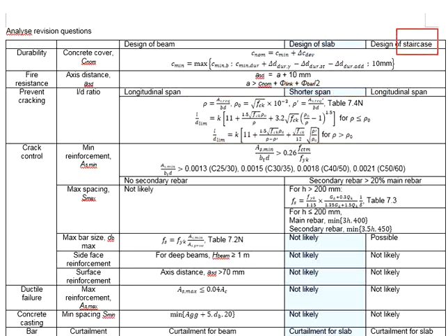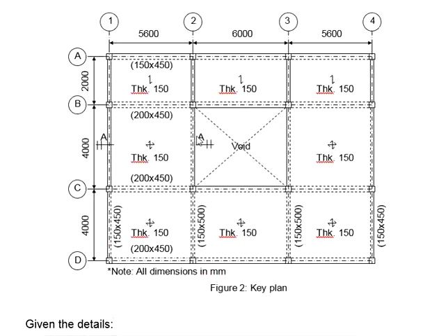As for the staircase, although in many aspects the design of the staircase is similar to a slab, due to its nature similar to the slab as a relatively large member, however, the support conditions of the staircase vary slightly from the slab. A typical RC slab is supported by beams at all edges. That means all four sides of the slab are supported.